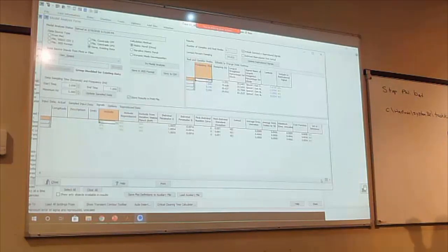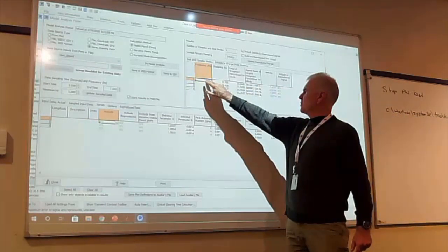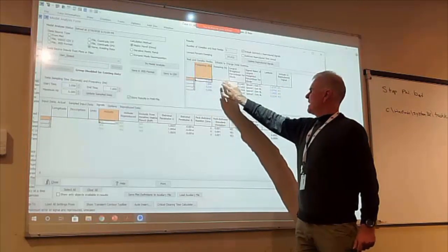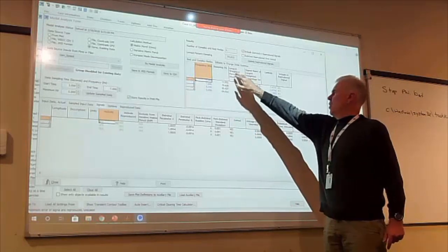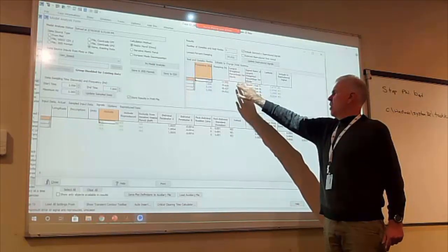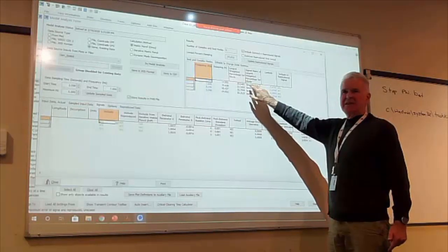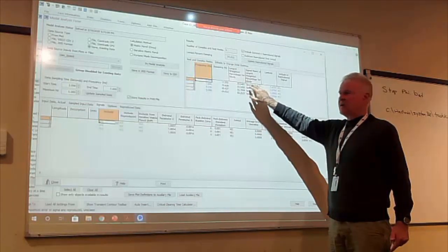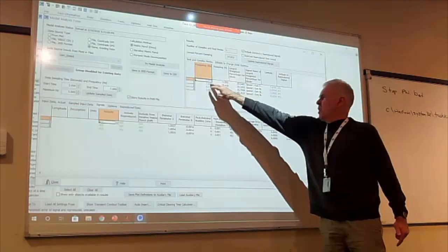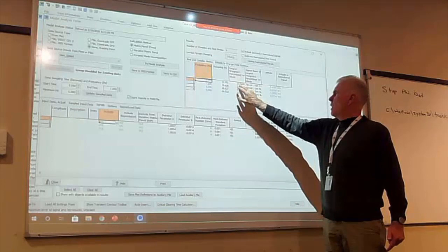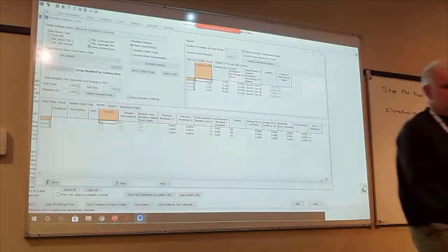The other way we could look at it is to say, for this 2 Hertz mode, it had damping of 11%. This is the largest weighted percentage for the mode, 25%, and it manifested in generator 3's speed. So this is now saying for each mode, what is the mode and damping that is common to all, what is the largest value, and what signal has the largest value?